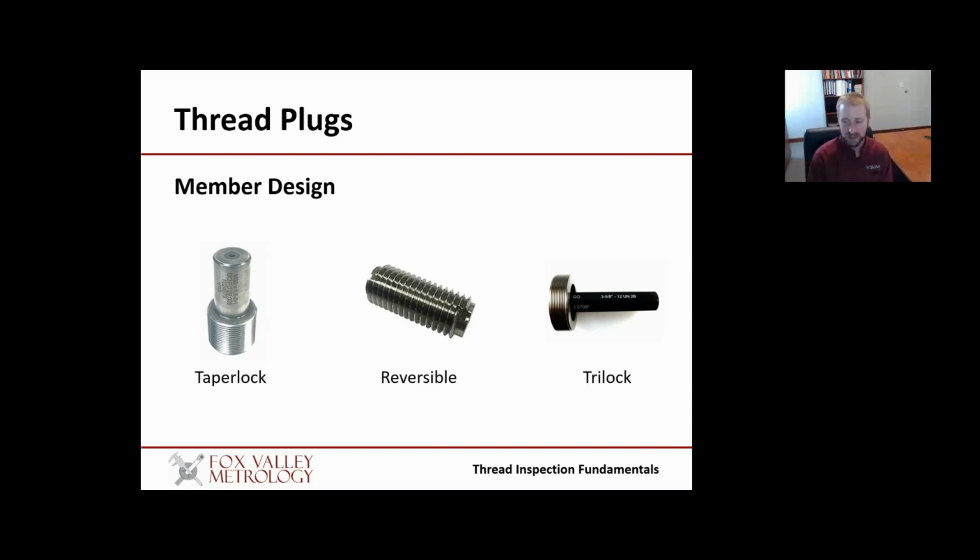So due to the size of these plugs, it's not uncommon at all to see them as individual plugs, as what's shown here, rather than having a go and a no-go on either end of it. Obviously, as those things get very large, they get heavy. If you were to put both members on the same plug itself, obviously that item would become heavy past a point of feasibility to use.